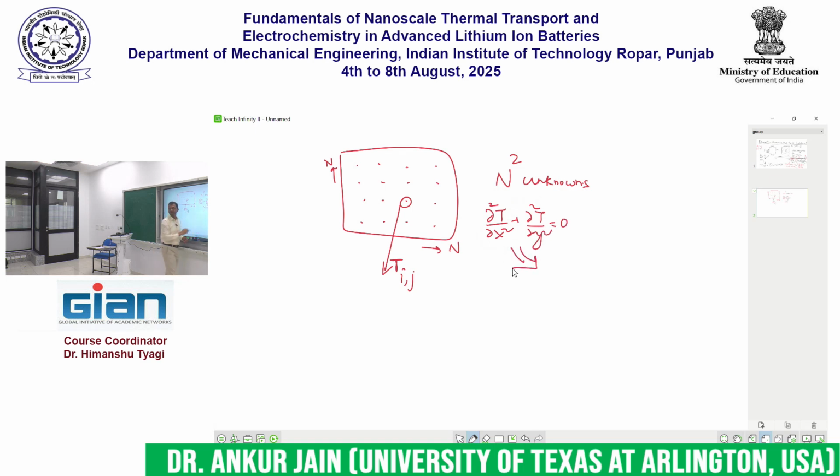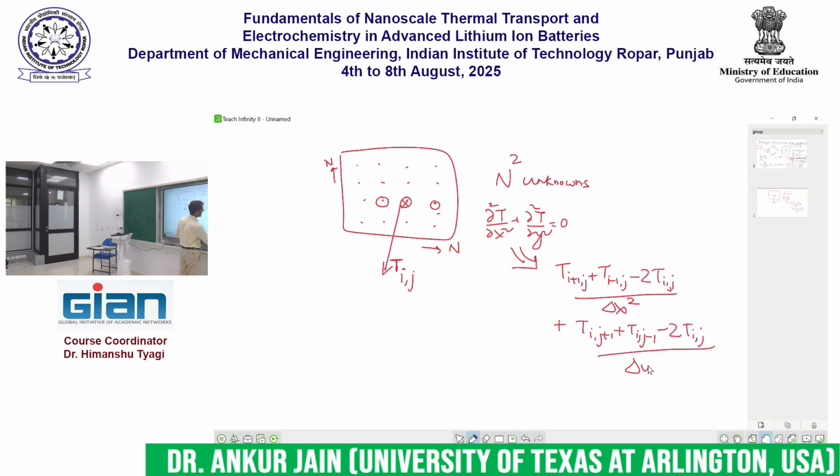which when I discretize will give me T(i plus 1, j) plus T(i minus 1, j) minus twice of T(i, j) divided by delta x squared. What is happening here is that I am looking at the neighbor to the right, the neighbor to the left, and where I am. Do you follow? T(i plus 1, j) is the neighbor to the right, T(i minus 1, j) is the neighbor to the left, and so on. This is d2T by dx2. As far as d2T by dy2 is concerned, that would be T(i, j plus 1), the neighbor above, plus the neighbor below, T(i, j minus 1), minus twice T(i, j), divided by delta y squared.